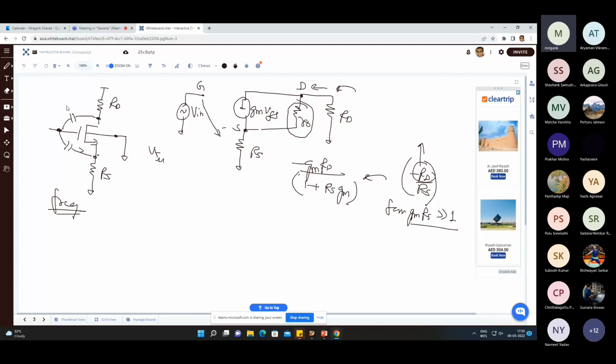So for this transistor, from VG to VD, we know the gain, which is a modified gain. We can figure out the Miller effect and break it down into a capacitance at the gate and a capacitance at the drain. Remember, the target is to get rid of this kind of capacitors which are coming between two circuit nodes. Likewise, in this case, this capacitor is also coming between two circuit nodes.